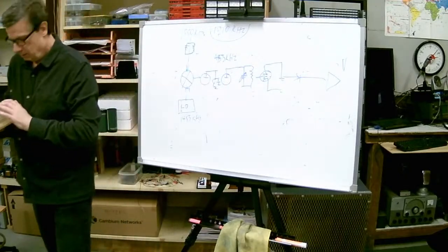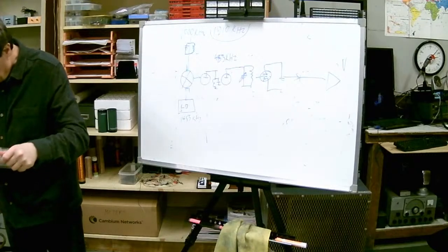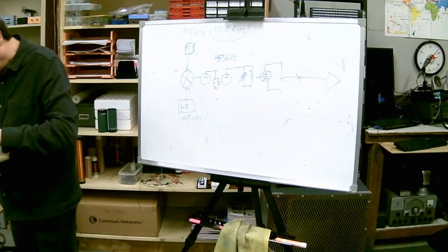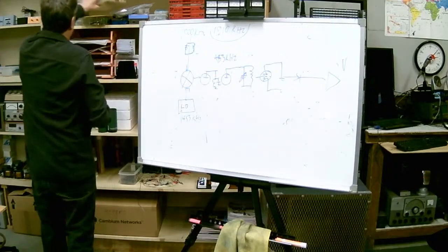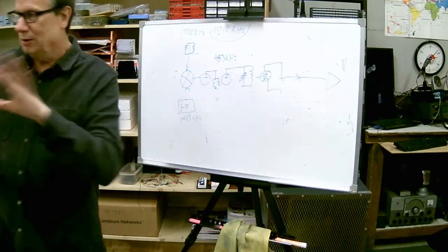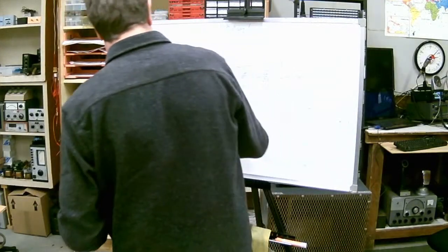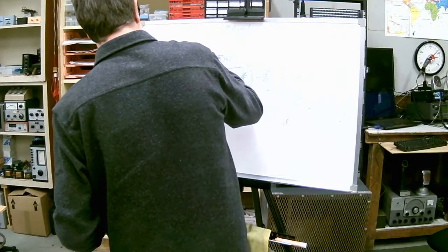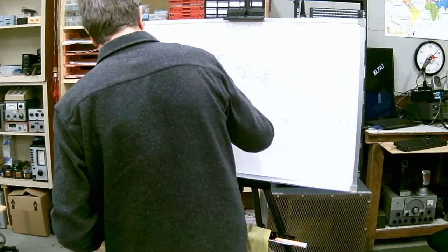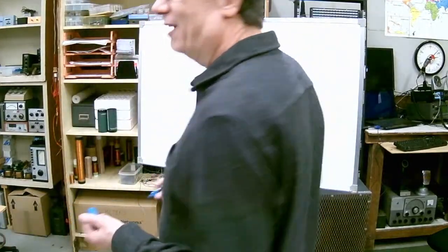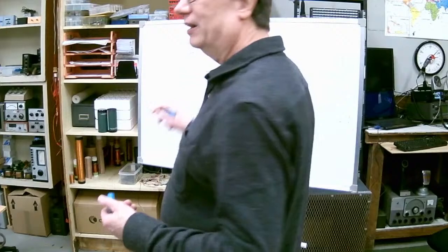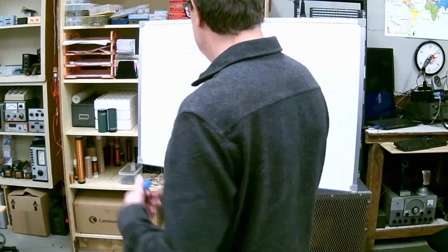Usually the local oscillator is higher in frequency than the incoming, so its capacitor plates would generally be a smaller set. And these would be ganged together. And anytime you see a dotted line in any schematic, it simply means a mechanical connection. So that means they're on the same shaft. But this one would tune at a different rate than that one, so it'd always keep the difference apart.